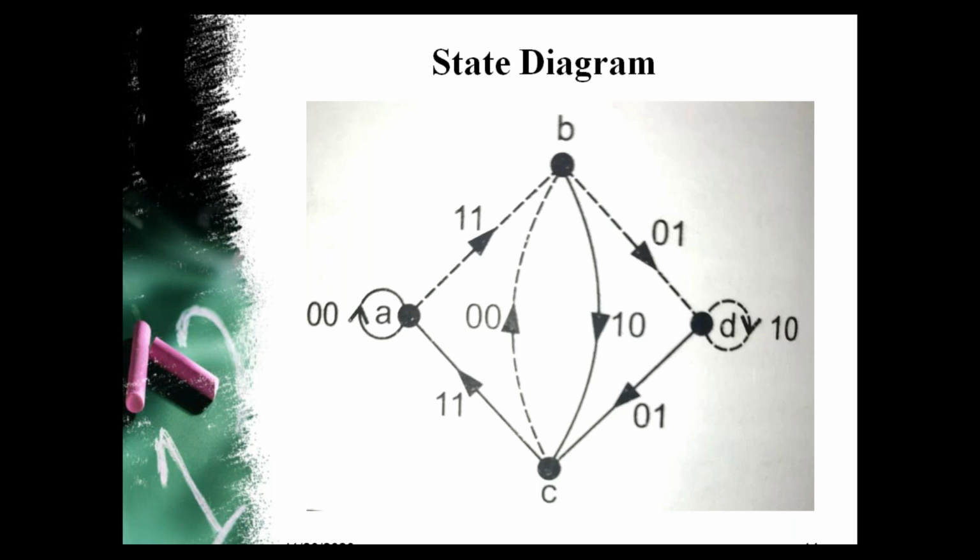It is once again a simplified representation, that state diagram. Here we represent all the states of the encoder only once. That is the difference compared to the trellis diagram. We have represented all the states of the encoder only once, that is A, B, C, D. The transitions drawn from one state to another are similar to the trellis diagram. If the input bit is 0, we draw a continuous line. If the input message bit is 1, then we draw a dotted line.